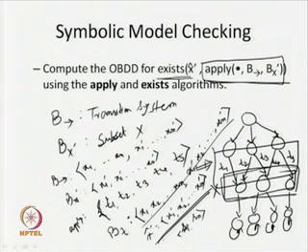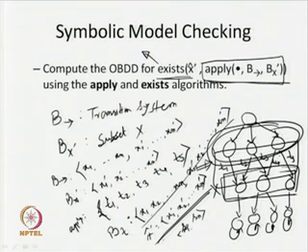So in the resultant BDD, whatever final BDD we get, it is independent of the next state variables. So eventually we get the representation of those states only. Just try to visualize it and understand it: we are getting these states only, represented by the present state variables. Whatever ROBDD or OBDD is returned by this operation gives us the OBDD representation of a subset of states from where transitions are coming into the subset X. Okay, so this is the way we are evaluating.